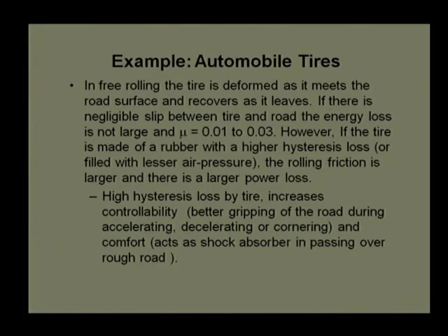But if we require very high reliability, definite life, definite fatigue life with high reliability, then in that case we should prefer the rolling element, or rolling friction, compared to sliding friction. When we discuss rolling friction, we are adding one more thing. When we take the example of a tire, we need to see whether the tire is completely filled with air or not.